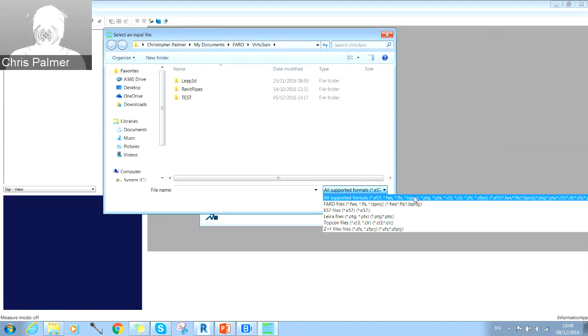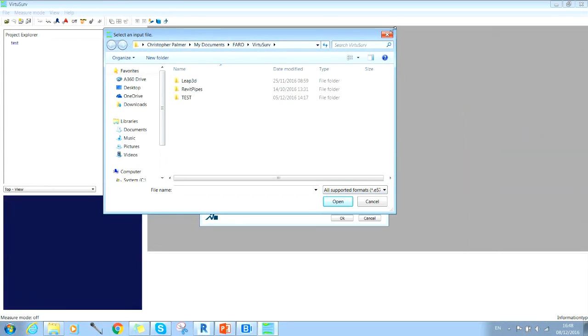And that does need to have the same coordinates as your RCS files or your RCP project in order to make the link work correctly. So really don't update your origin in ReCap if you're going to be using this link. Is this the answer? Okay, thanks, Chris.